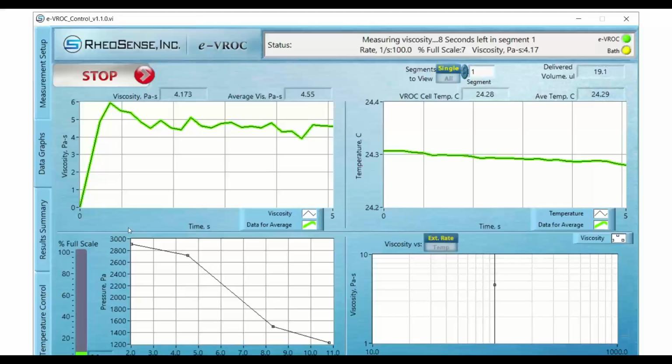So what you want to look at here is, this general form that we're seeing now looks like a good flow profile. And by that, I mean the slope, visibly, and we can confirm it later when we analyze the data, the slope visibly of the 2 pressure sensors prior and after the contraction are approximately the same, and they're not erratic, bouncing about. They're reasonable there. And then we have this larger pressure drop through the extension. So that's one of the things you want to look for when you're doing this type of experiment.